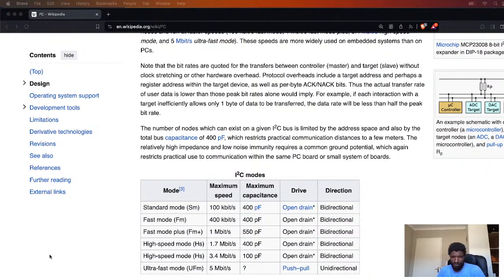So yeah. And then another thing that we had in SPI was we did not have an acknowledge, or rather there was a lot of dummy reading. If you needed to read a packet, you'd send a packet and then you dummy read, and then you would read the actual, because every time you sent data in SPI, the data going out caused some data to come in this way, which could be dummy, which could be not what you want.